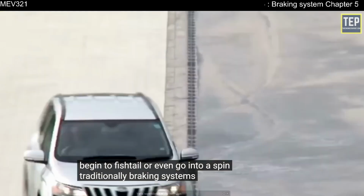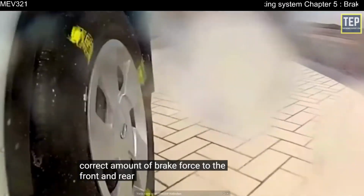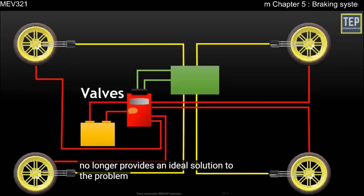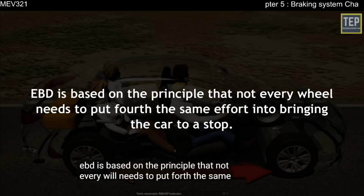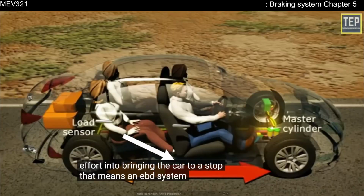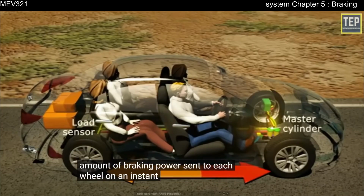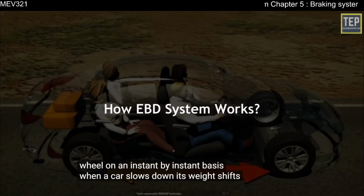Traditionally, braking systems included a proportioning valve to allocate the correct amount of brake force to the front and rear tires. However, with ABS, the proportioning valve no longer provides an ideal solution to the problem. EBD is based on the principle that not every wheel needs to put forth the same effort into bringing the car to a stop. That means an EBD system can not only detect how much weight is being supported by each wheel, but change the amount of braking power sent to each wheel on an instant-by-instant basis. When a car slows down, its weight shifts forward.